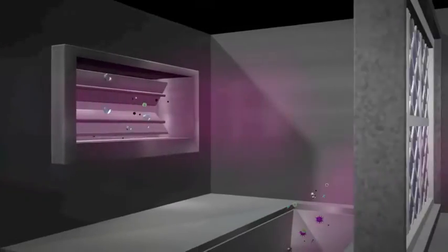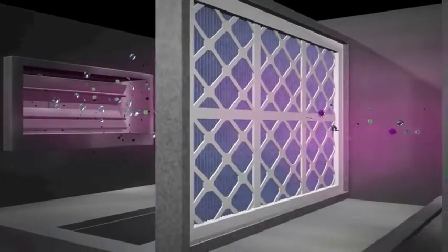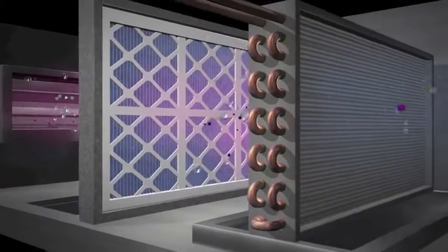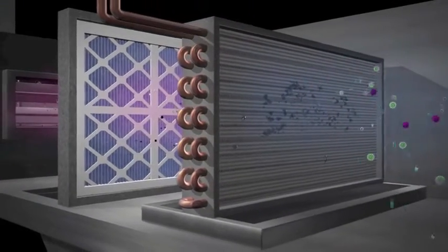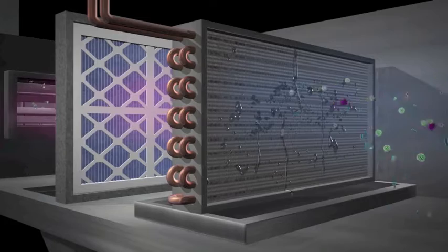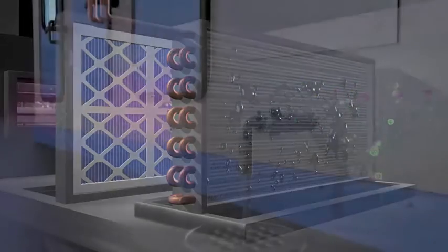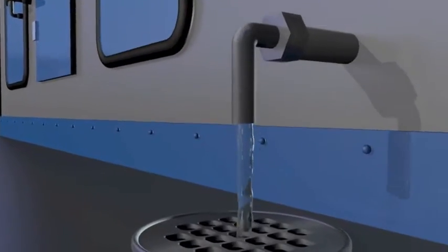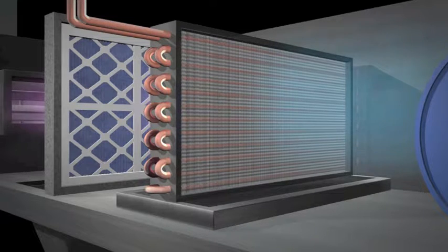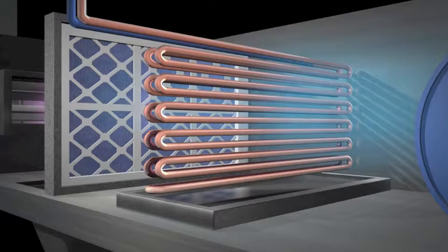A percentage of fresh air is then added. This mixed air is passed through the primary filters to remove big dirt particulates. The resulting condensate in the cooling coil is drained away to the sewer. The heat from the building's air is absorbed through the coil fins by a cold liquid, typically chilled water, that is being pumped through the coil.